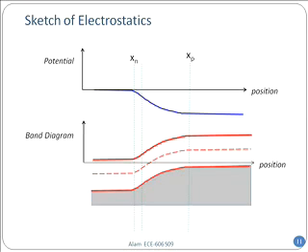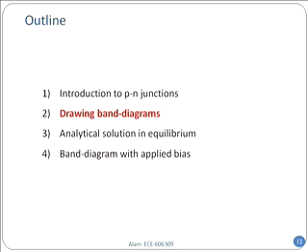In the bulk region on the far left, it looks like a typical N device. In the bulk region far to the right, it looks like a typical P device, donor doped, acceptor doped device, when something is happening. But the issue here is that this line, which is like an arrow, this is the Fermi level. In equilibrium, Fermi level must be flat. That's the statement. And then off equilibrium, we'll see how it comes about.